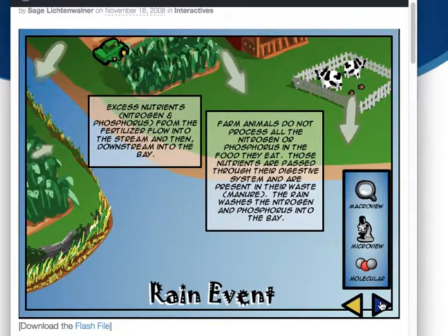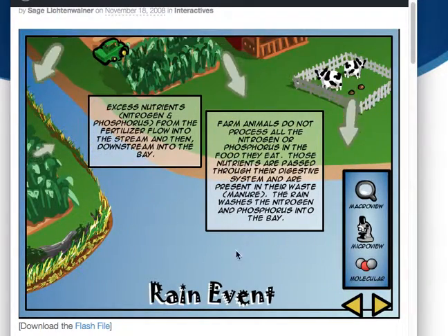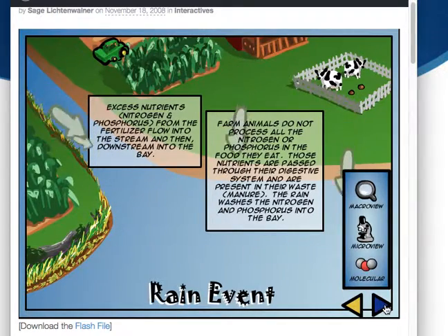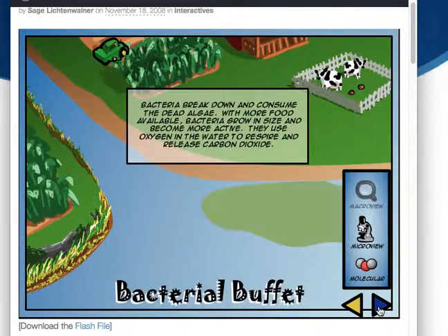It's going to begin with inputs from fertilizers on these lawns or from animals in the vicinity, and they're washing nitrogen and phosphorus into this waterway. The nitrogen and phosphorus are typically limiting nutrients in these environments, and so they cause a growth of algae when they're added to the system. Those algae grow, they shade one another out, and they eventually provide food for bacteria in the system. So we see a huge spike in bacterial growth in that waterway.